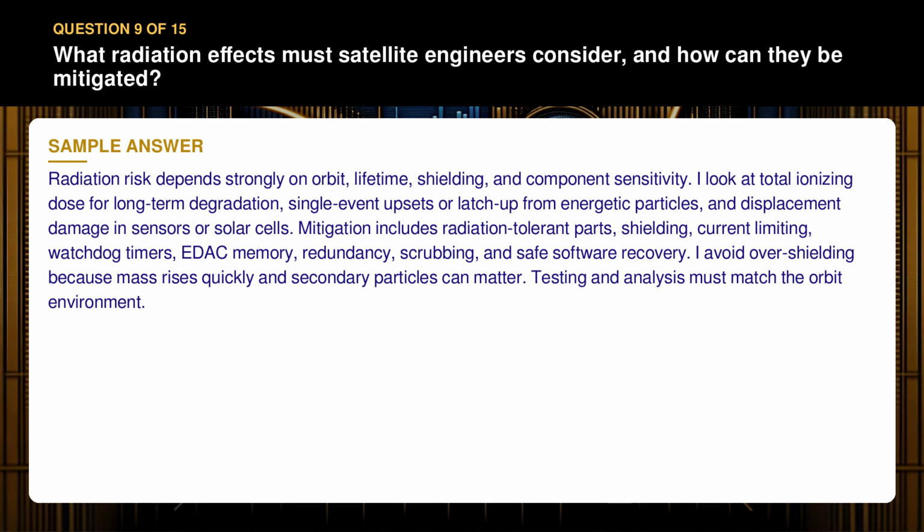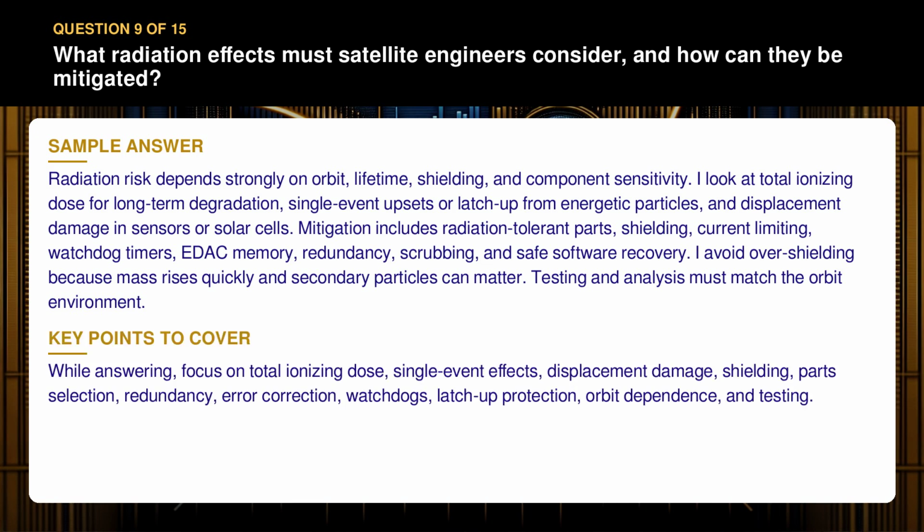Testing and analysis must match the orbit environment. While answering, focus on total ionizing dose, single event effects, displacement damage, shielding, parts selection, redundancy, error correction, watchdogs, latch-up protection, orbit dependence, and testing.